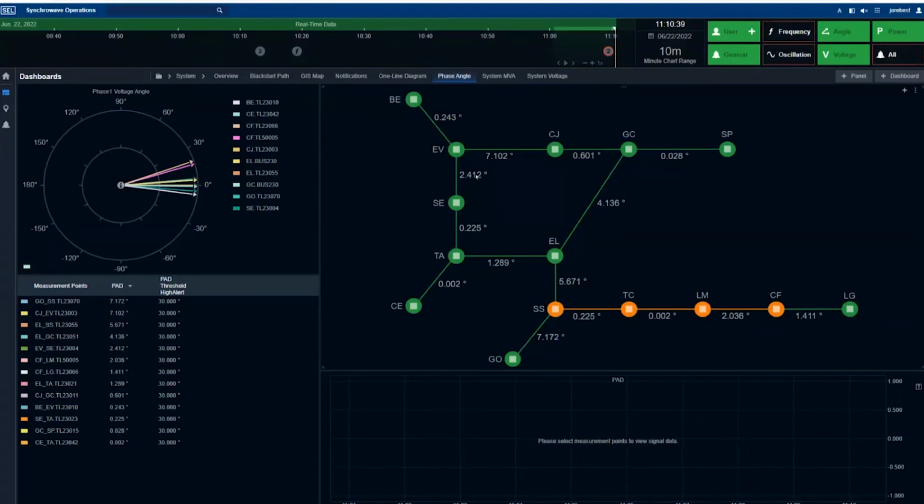And so what you can see here, for example, is we might have a phasor scope showing the stress across my system, or I might be monitoring a point of interconnection, whether that's for a microgrid or an industrial facility. I might be interested in that. And then over to the right, maybe from more of a utility perspective, I'm displaying the phase angles across core transmission lines within the system, so I can have that visibility at any point in time and know if there are any phase angles that are exceeding particular limits, for example.